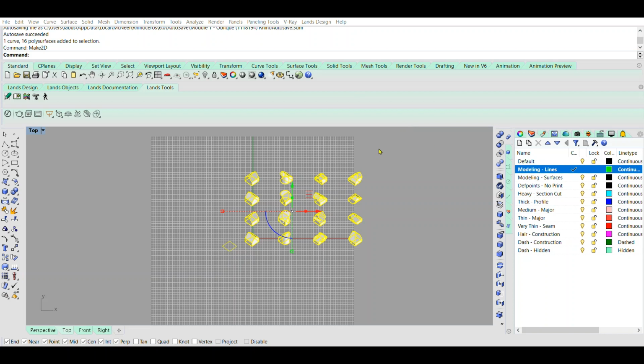And then we will keep off the tangent edges, viewport rectangle, group output, and everything else. And then the layer name we'll just keep as Make 2D. But the two crucial ones are hidden lines and scene silhouette. And then just make sure you keep maintain source layers on. That'll help you organize all of your Make 2D layers, and make sure your output's very clean.